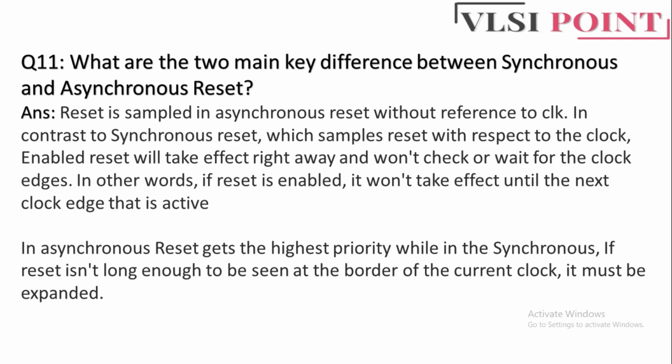However, asynchronous reset, on the other hand, does not use a synchronized reset signal. Instead, the reset signal is applied directly to the reset input of each element of the circuit. This can cause timing issues because the reset signal may arrive at different times for the different elements, leading to glitches or other problems. So this is the major difference between the synchronous and asynchronous reset.